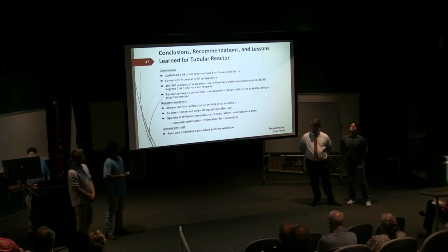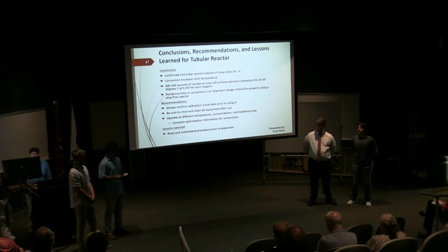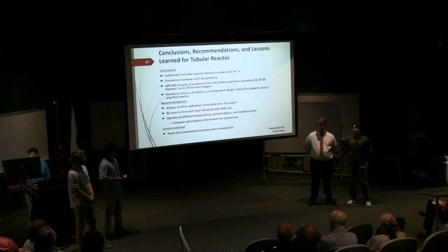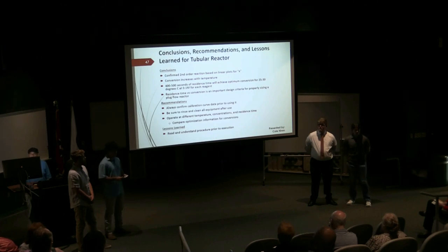Here are some of our conclusions, recommendations, and lessons learned from the tubular reactor. We confirmed second order reaction and conversion increases with temperature. There are 400 and 500 seconds of residence time, and residence time versus conversion is an important design criteria.